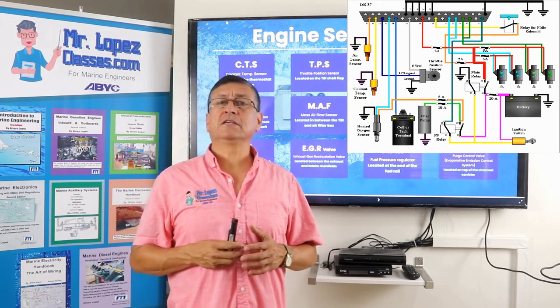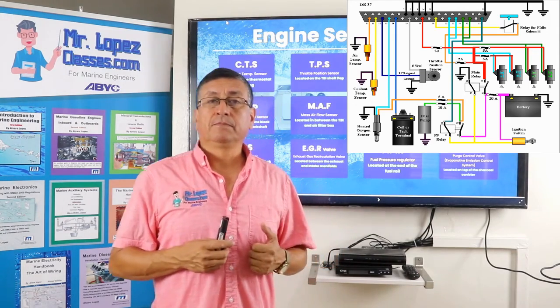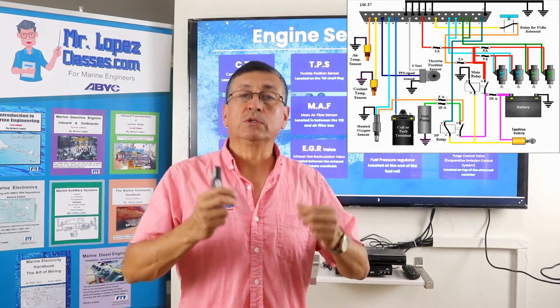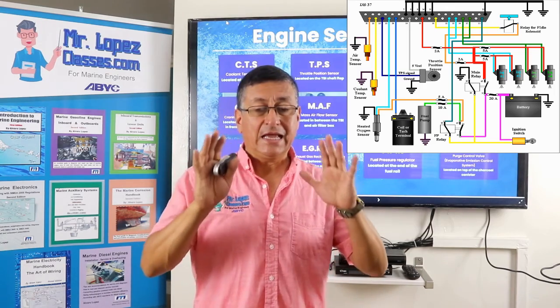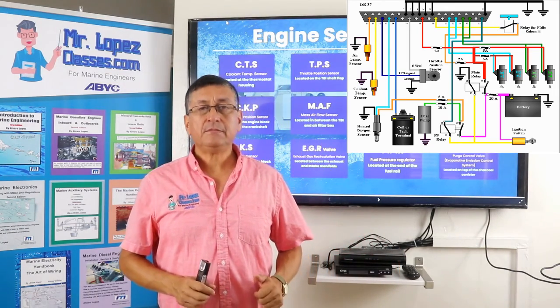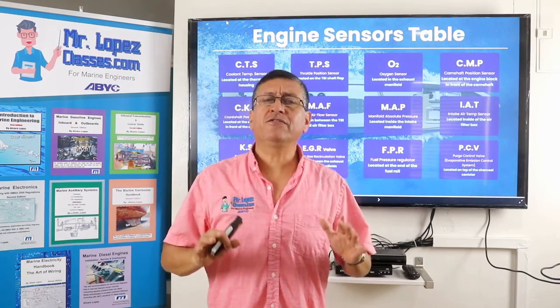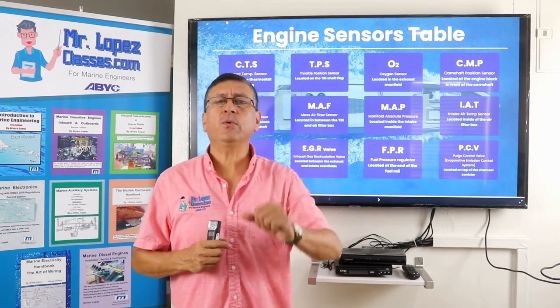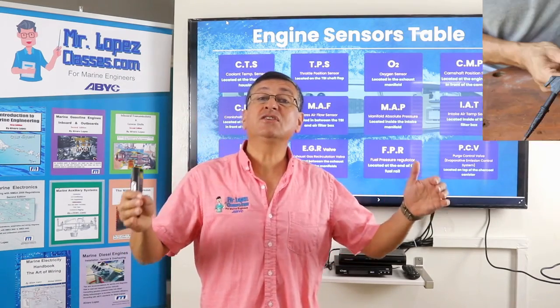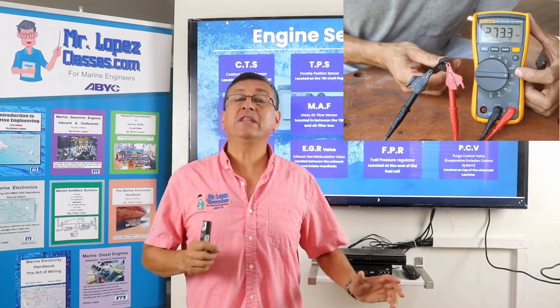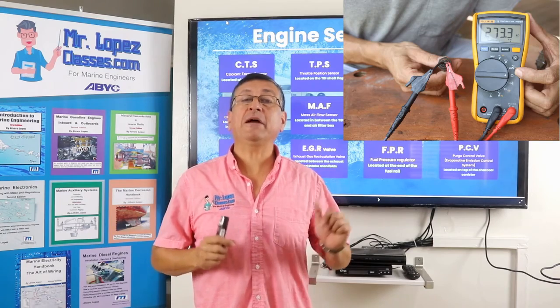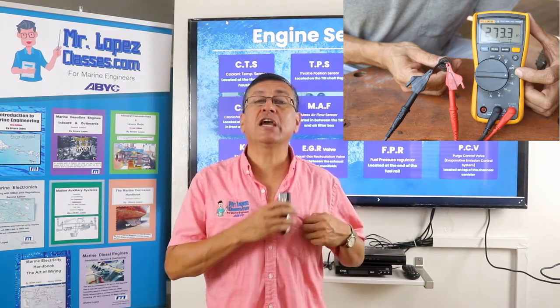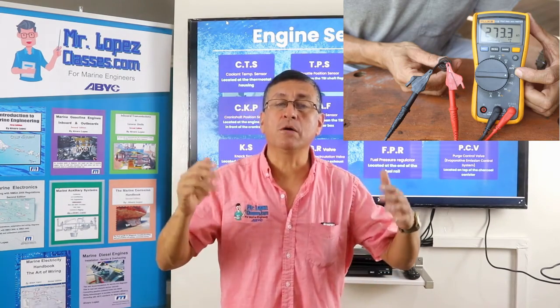For that reason, my friends, I recommend you try to prepare tools to check the sensors. Let me explain something. Normally, the majority of the sensors can be checked in two ways. The first way is when the engine is off. When the engine is off, the majority of the sensors can be checked with resistance, with ohms.